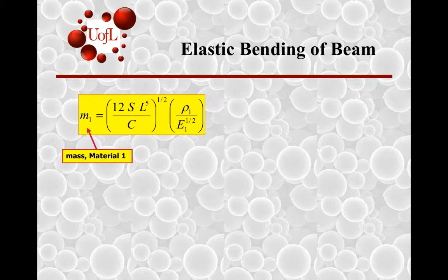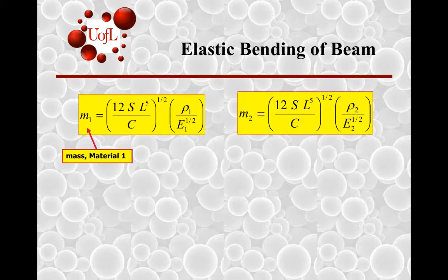Let us apply this set of equations where you have the mass of the material expressed as a performance index, as a product of the functional requirement, the geometric requirement, and the material index. So if M1 is given by this and M2 is given by this, two materials, right? So M1 would have properties based on one material.